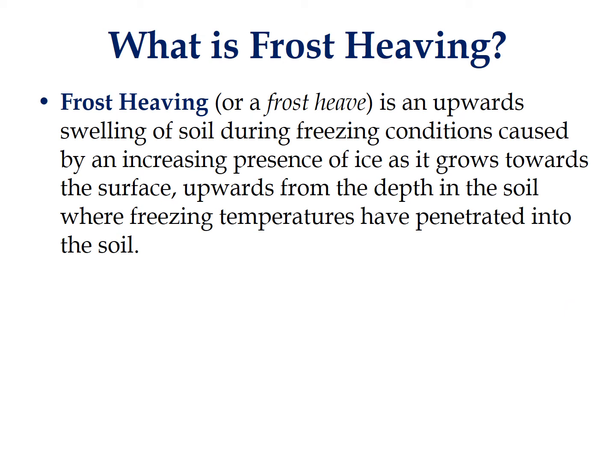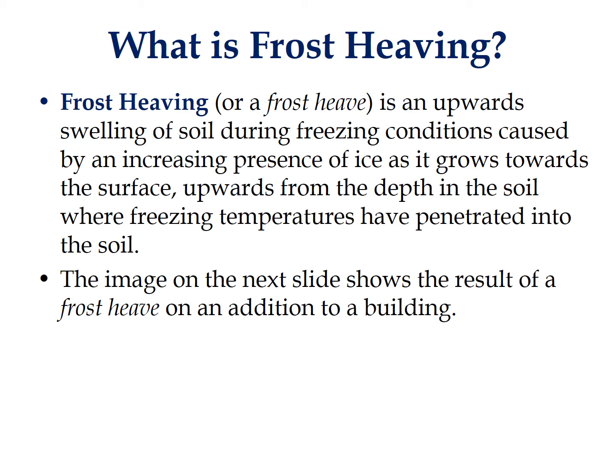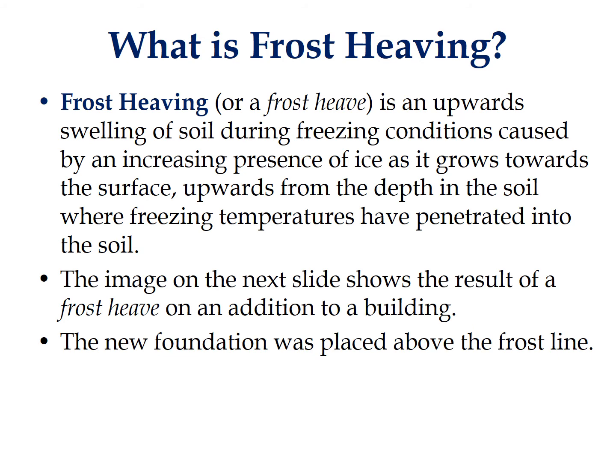Frost heaving, or a frost heave, is an upward swelling of soil during freezing conditions caused by an increasing presence of ice as it grows towards the surface upwards from the depth in the soil where freezing temperatures have penetrated into the soil. The image on the next slide shows the result of a frost heave on an addition to a building. The new foundation was placed above the frost line.